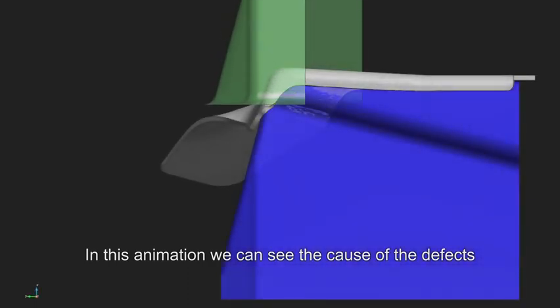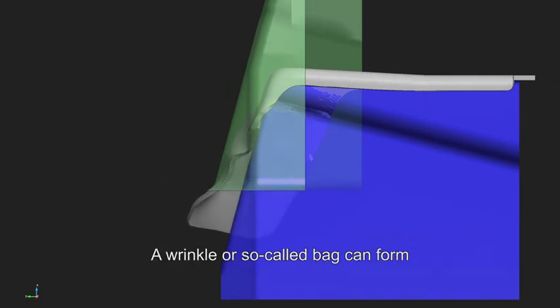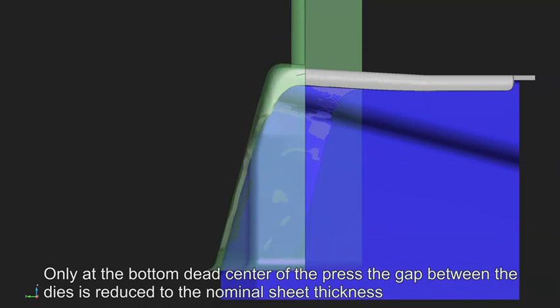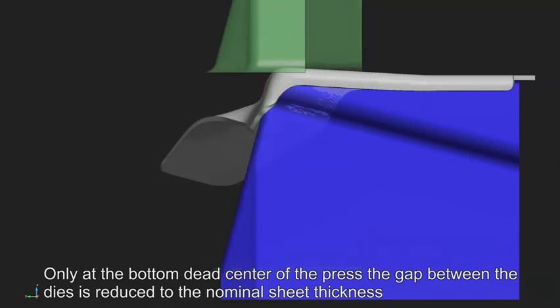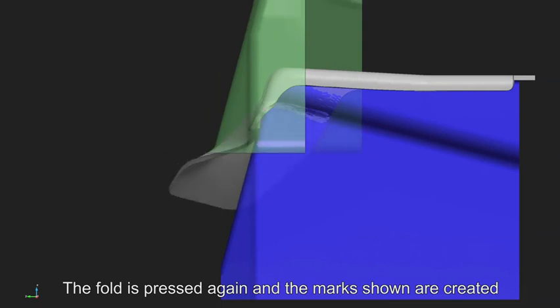In this animation we can see the cause of the defects. Due to the set angle there is space between punch and die. A wrinkle or so-called bag can form. Only at the bottom dead center of the press, the gap between the dies is reduced to the nominal sheet thickness. The fold is pressed again, and the marks shown are created.